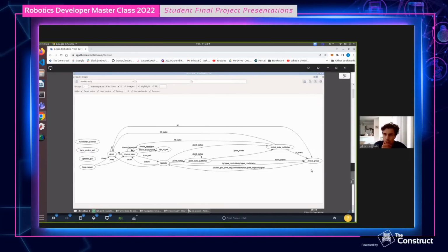This was one thing, and that's the only thing really that I've changed for the navigation. Oh yes, for the odometry, I needed to get my odometry topic. I don't have the same odometry topic. I've got my odometry from a laser scan matcher. Basically, I'm getting the odometry from the LiDAR.